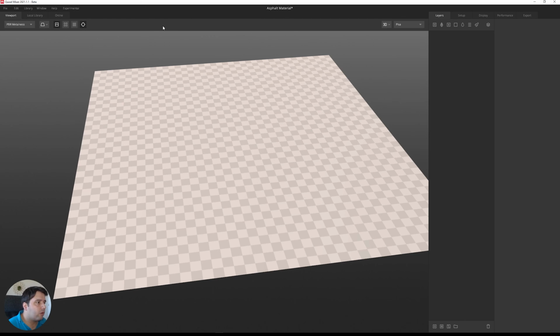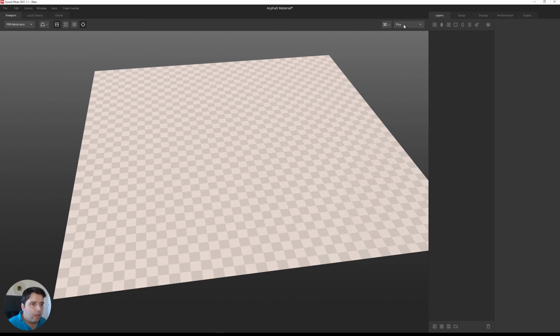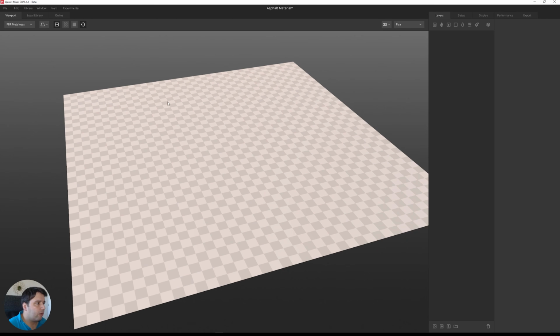So let's go here to layers, and here you can see that I'm choosing the 3D view, but you can also work in the 2D view. And you can select different types of HDRIs, so you can see different types of lighting. And you also have other options here, like previewing the displacement. So you can disable this if your computer is not handling the displacement well.